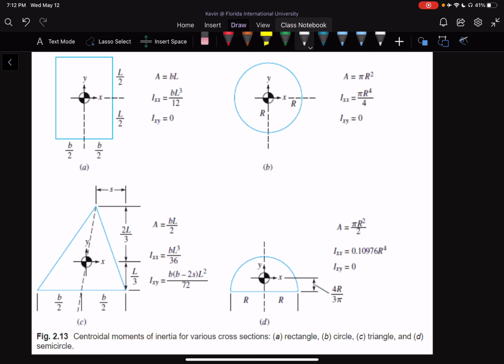And then it's up to you to decide: can I make the assumption to omit atmospheric pressure? If the plate is in contact with the atmosphere on the side you're trying to find the force on, then you can be pretty sure you can omit atmospheric pressure. If it's completely submerged in water, or in oil or any other liquid, then it will be harder to omit atmospheric pressure.